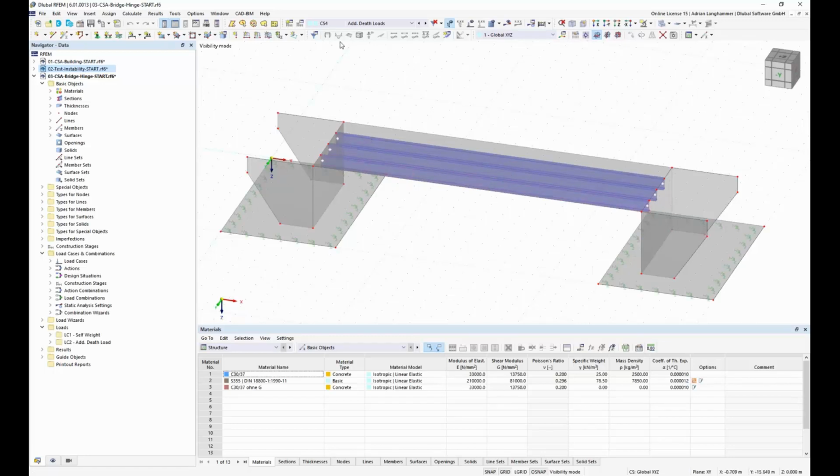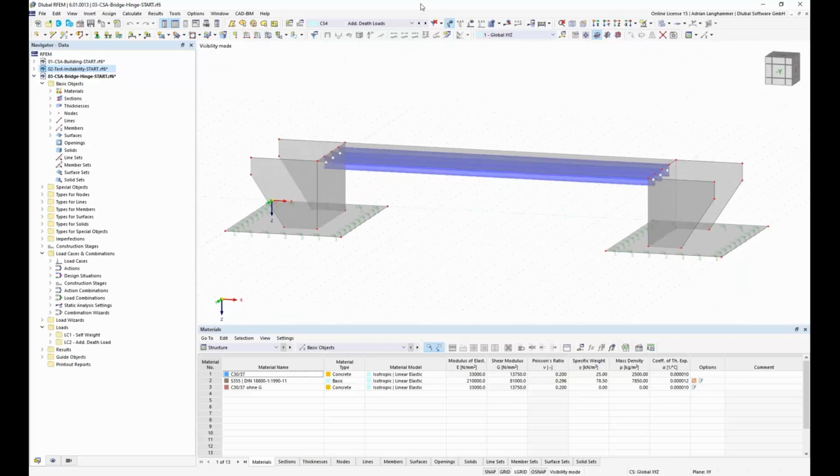While activating the concrete slab in the last construction stage, I would also like to change the connection of the steel girders, so they should change in the last construction stage from hinged to rigid, because you have the concrete over these steel girders, and the connection will be rigid. So to do this, I open the last construction stage,